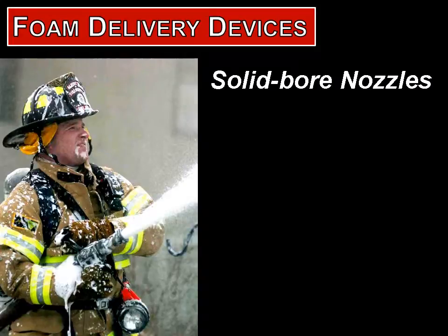Foam delivery devices. Solid bore nozzles are limited to certain types of Class A foam application, most often used with compressed air foam systems. Because your finished product is already made when it comes out of the pump, you can use your solid bore nozzles for delivering your Class A foam.